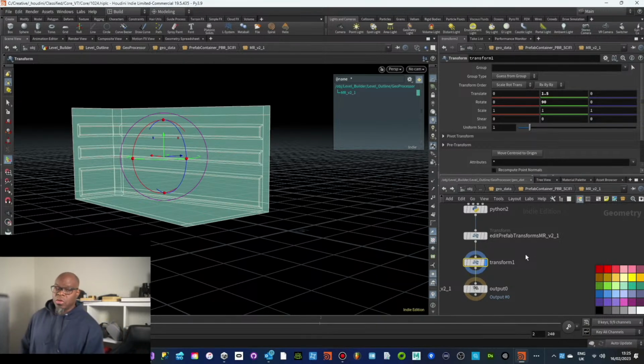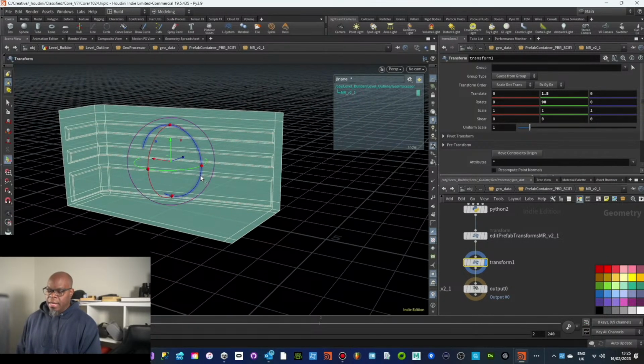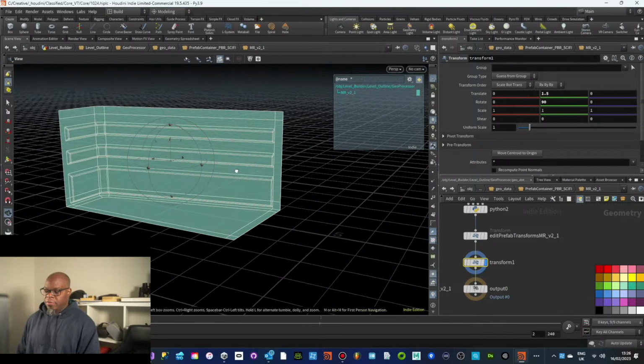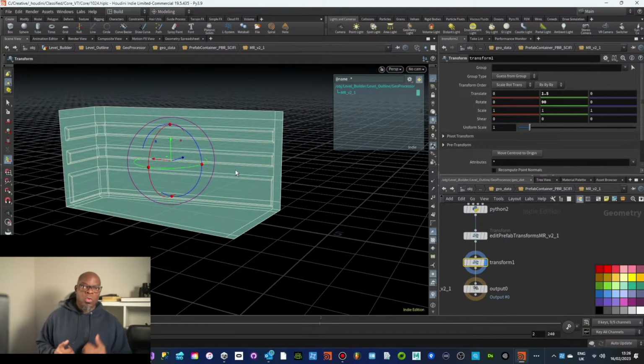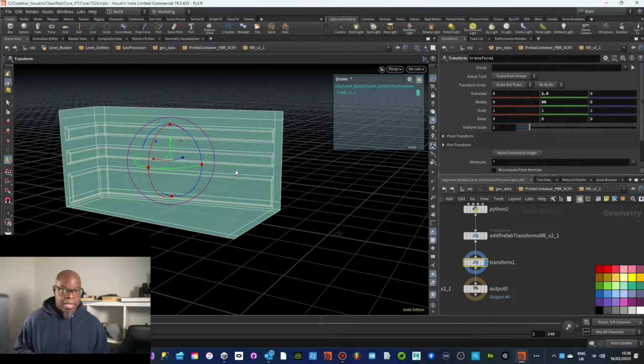Okay, so at the moment you're looking at an asset here that has been brought in from Unity into Houdini, and the pivot point is not at origin. That's perfectly fine. It's just more the principle that if you do the import, you need to accommodate that in some instances the pivot point was set by the author of the asset at origin, and for some they don't. And you don't automatically get that information when you export it from Unity and then pull it across.